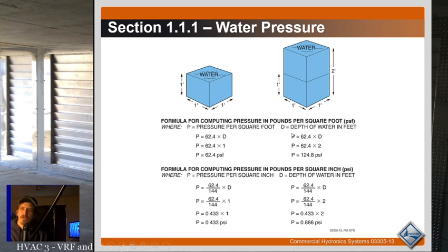I generally don't calculate this like this, but I usually try and convert the amount of water to gallons, and then it's like, what, I don't know, I'd have to look it up. I got it somewhere. It's like 7.5 pounds per gallon, and then 8.33 gallons per cubic foot or something like that. I'll see if I can pull it up before we're done, but I usually calculate the volume and then figure out how many gallons and multiply it by the weight of water per gallon.